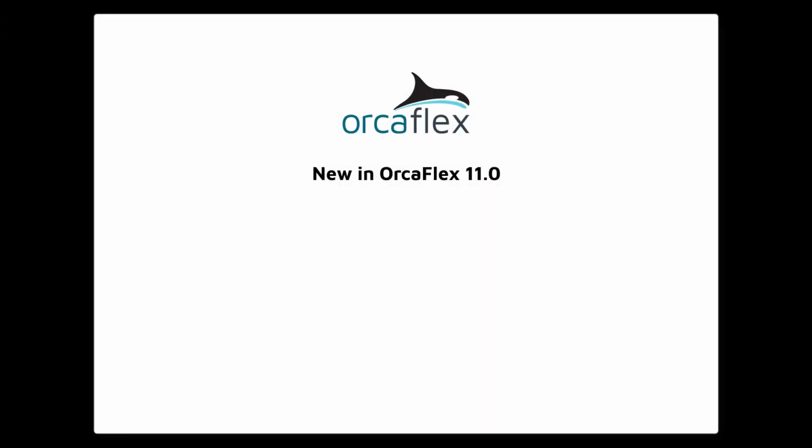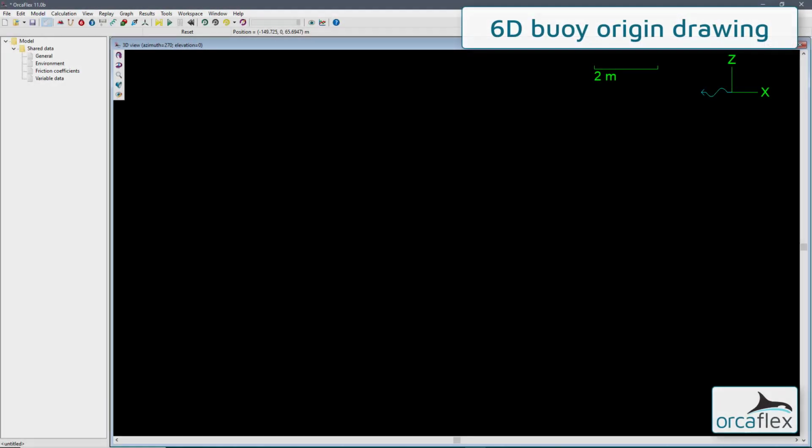We will now look at some improvements to the general user interface. The first of these is vessel and 6D buoy origin drawing. We will look first of all at the new options for drawing origins in the 6D buoy object. If we insert a new 6D buoy into this model, it is of course the lumped buoy type by default, and you will see a blue cross at the centre. This represents the centre of volume of the buoy.